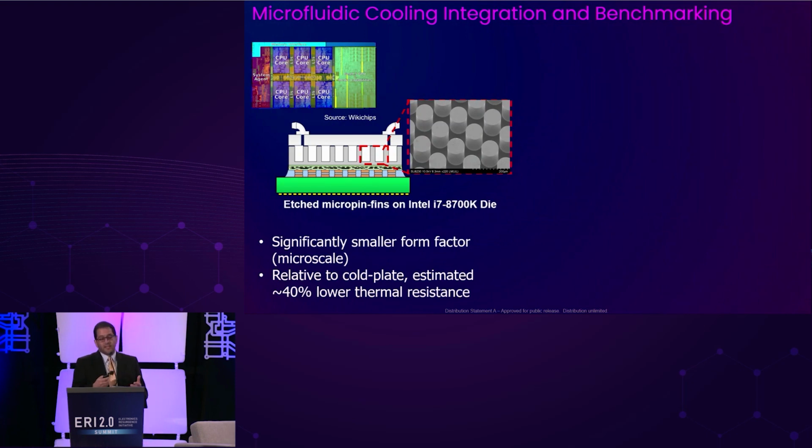We have successfully integrated such cooling technologies in active silicon. Here we show an Intel i7 processor that has been post-processed with the monolithic microfluidic cooled heatsink, and measurements demonstrate approximately 40% lower thermal resistance compared to a copper plate solution.